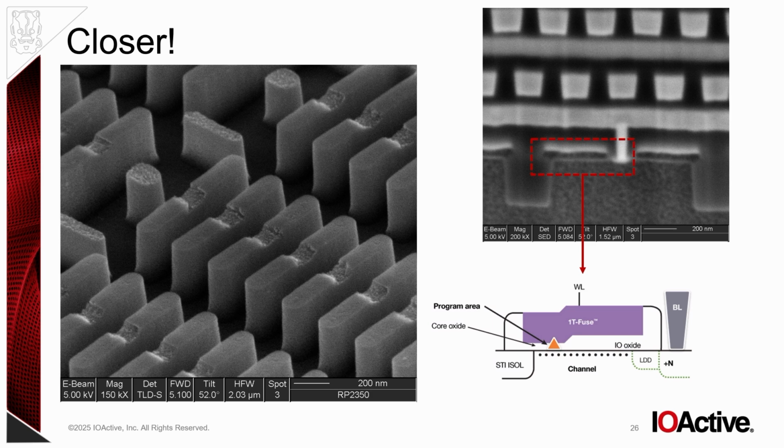So if we look on the right, we start to see things that look a bit like our cross-section from the Synopsys website. We don't have enough resolution there to really see everything, but you can see this hump is one of these humps on the left, and it looks like this area here. And then this big lump on the top is the polysilicon, which is sitting on top.